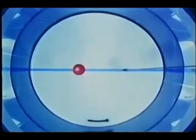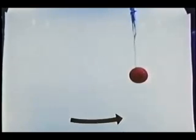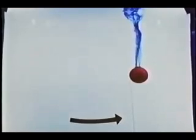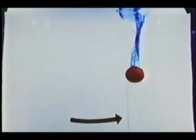The reasons are associated with the flow pattern around the sphere. Here we are looking from the side. Dye crystals leave traces which mark the fluid over the ball. When the ball is towed away, it does not leave all the dye behind, as we might expect, but instead carries a column of fluid with it.